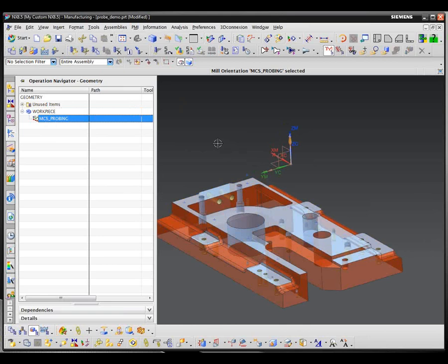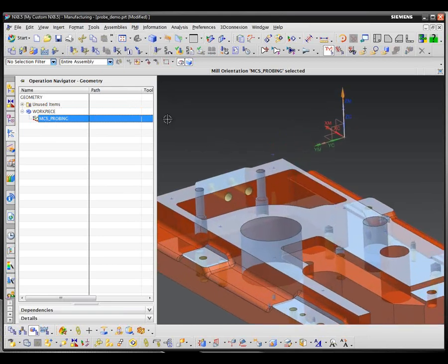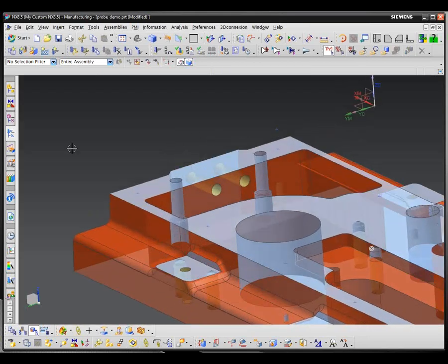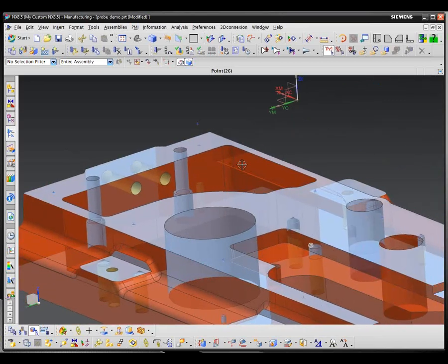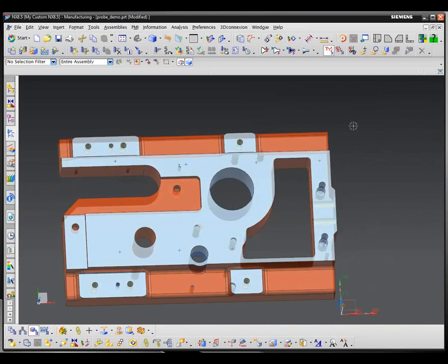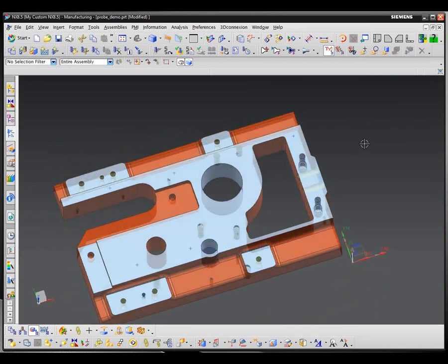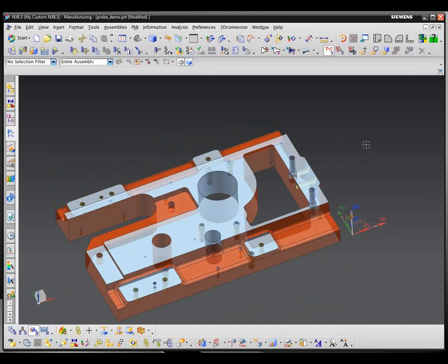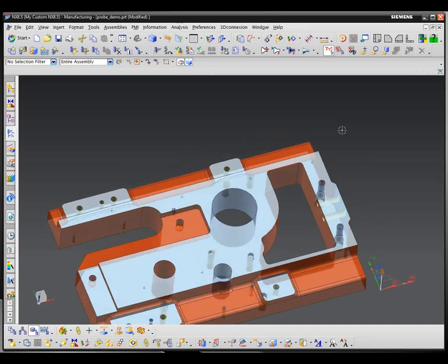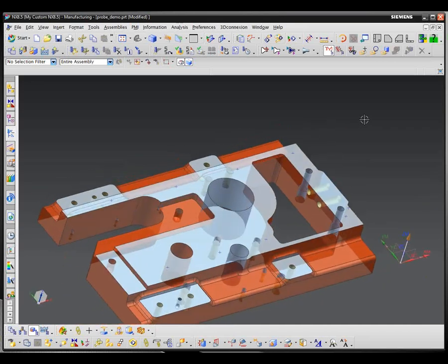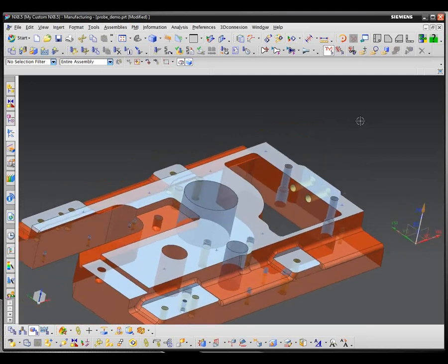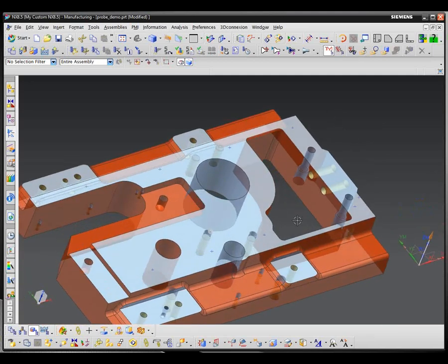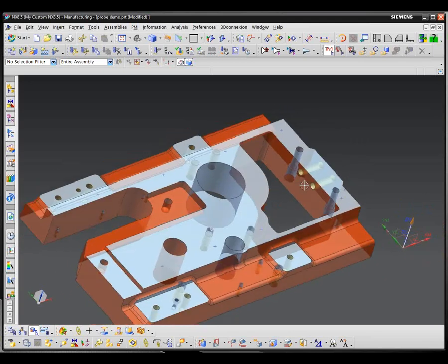Okay. And the only extra thing, I think it might be easier for probing purposes to have a set of points out here. It's not necessary, but at times they call out definite datum targets on your blueprints, so you might use that. I don't know, I'm kind of picky, so I like having a nice neat pattern there to probe with.